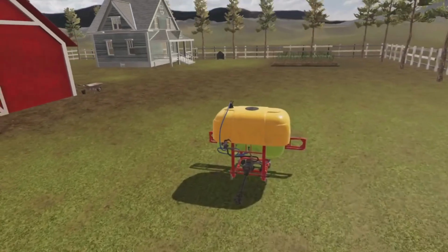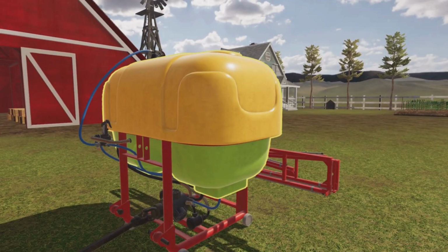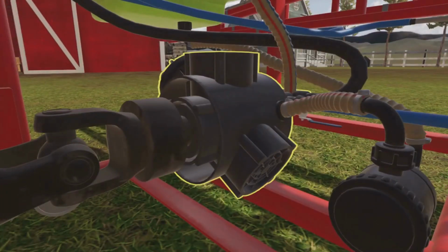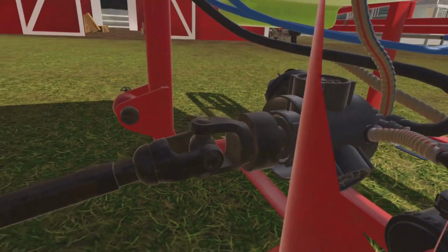Sprayer parts. Chemical tank. The main compartment where the agricultural chemical is stored. It is usually made from polyethylene or stainless steel and comes in various capacities. It features a strainer and a cap for secure storage. Pump. The component responsible for transferring the liquid from the tank to the spraying system under pressure. Typically, piston or diaphragm pumps are used, powered by the tractor's PTO.